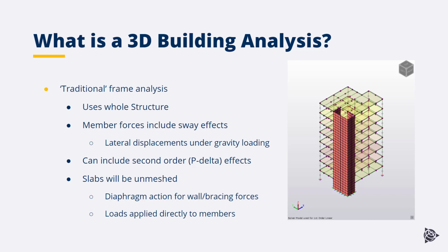This will allow for a worst case loading to be decomposed to the supporting beams by forcing these members to take all the load that has been applied to the slabs. This means that by default there will be no forces and moments in the slabs, so these slabs will not be designed using this analysis.